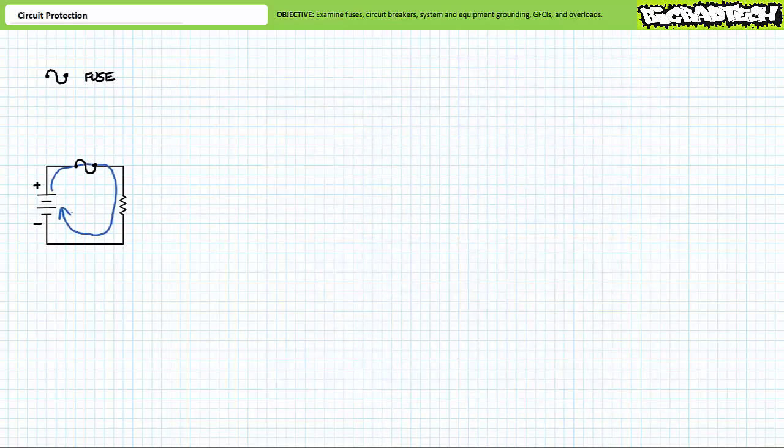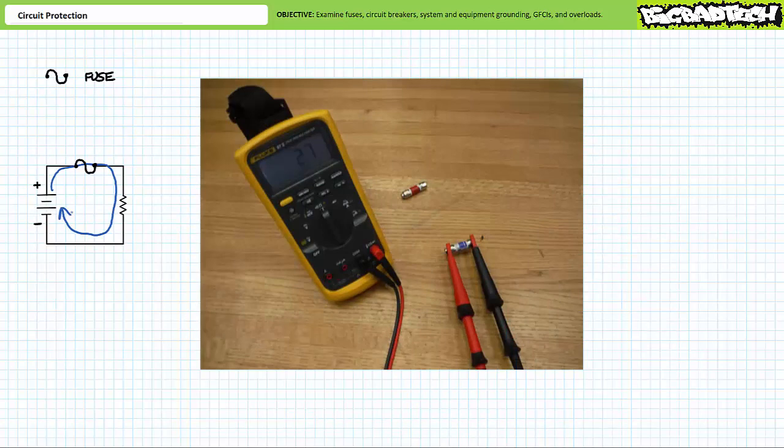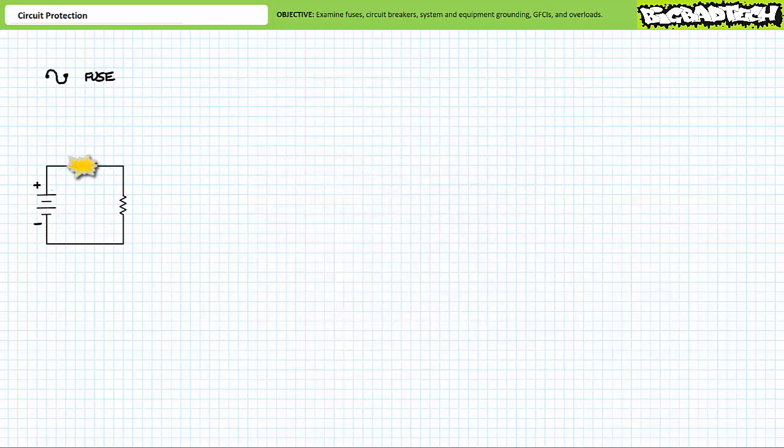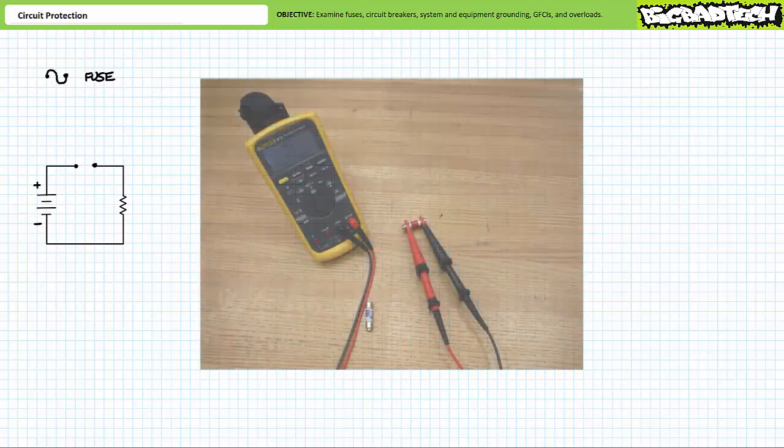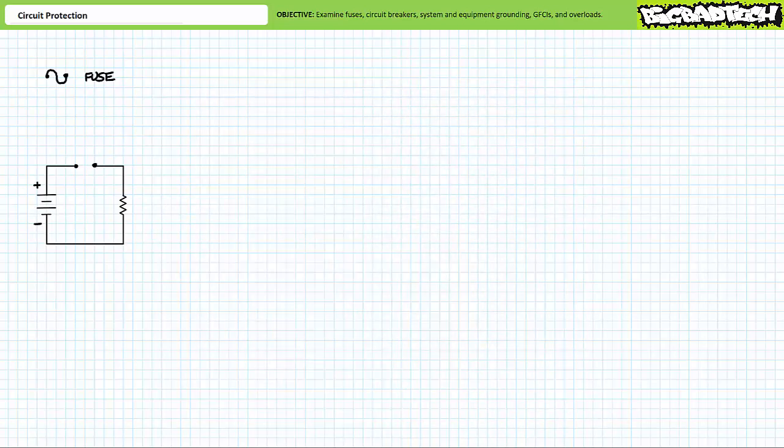When the fuse is intact, the path between its two terminals is a closed 0-ohm path and the circuit operates as intended. An ohmmeter demonstrates this fuse is intact. When current reaches or exceeds a certain predetermined value for a certain amount of time, the fuse melts and the path between its terminals opens and stops current flow by becoming an infinite resistance. An ohmmeter demonstrates that this fuse is blown. Fuses, like hand grenades and your virginity, are one-time use only. When a fuse blows, it is rendered permanently inoperable. Fuses come in two varieties, fast blow and slow blow, which are indicators of their reaction time.